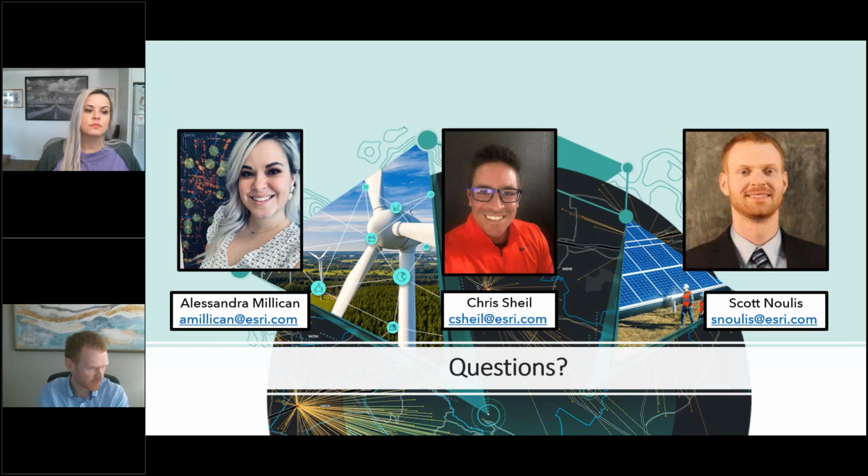We do. We have a few data sets in the Living Atlas. I didn't touch on them today, but specifically we've got a transmission line layer that is sourced from basically the national government and the data that they're collecting. That's a vector layer, right? So it's just a line layer that's a web service through the Living Atlas. You could certainly use that as an input to a raster analysis tool to generate, let's say, a proximity to transmission layer that looks at the varying distances from that line location as you move out.